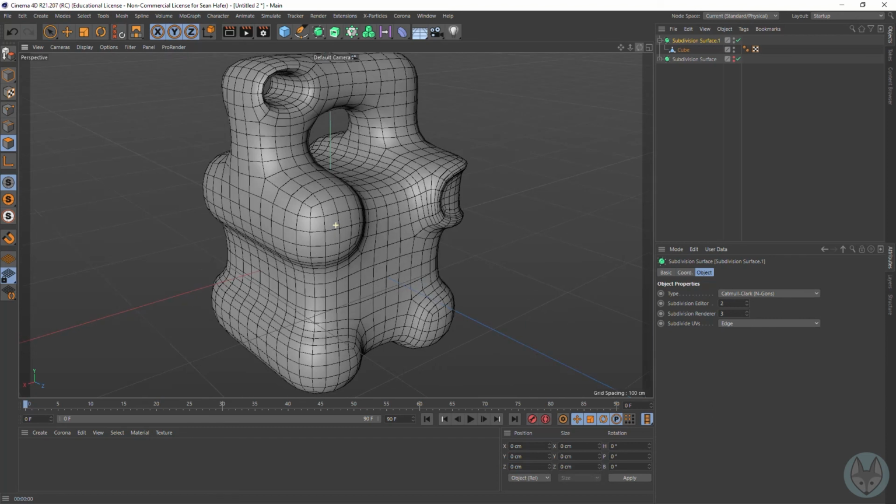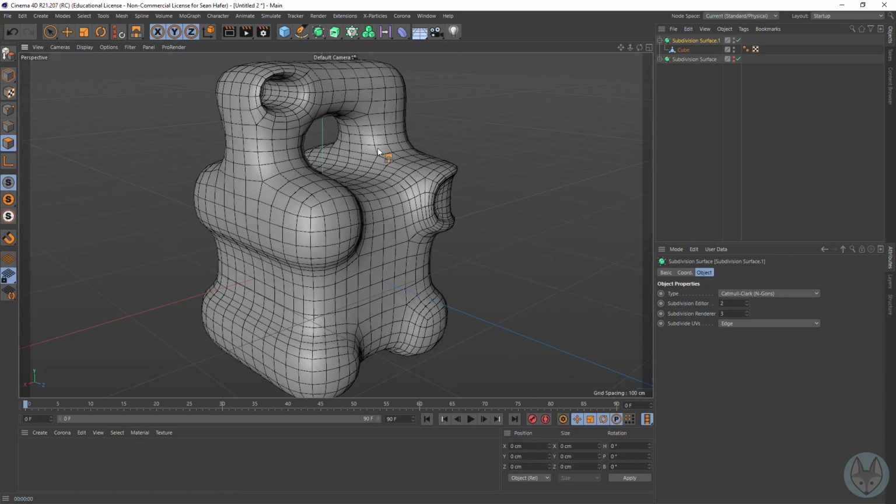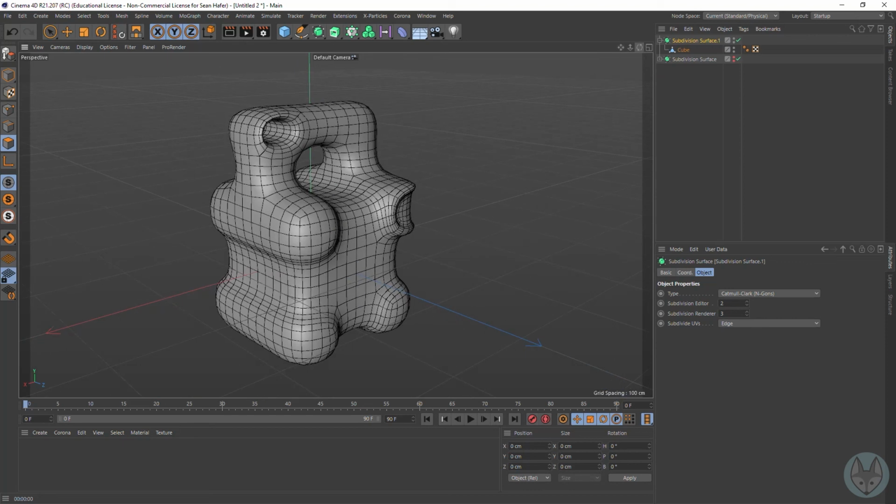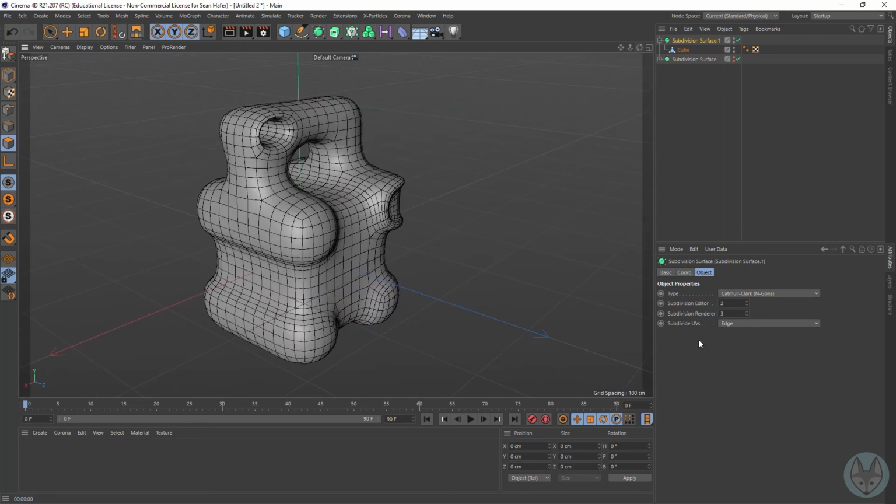All right, so in this I talked about non-uniform rational B-splines, and that's the NURBS math that it's using to create this smoothing effect from a subdivision surface. I also talked about different spline types to demonstrate how that influences the edges versus having the edges flow through the points, creating our smooth surfaces and our curved surfaces.